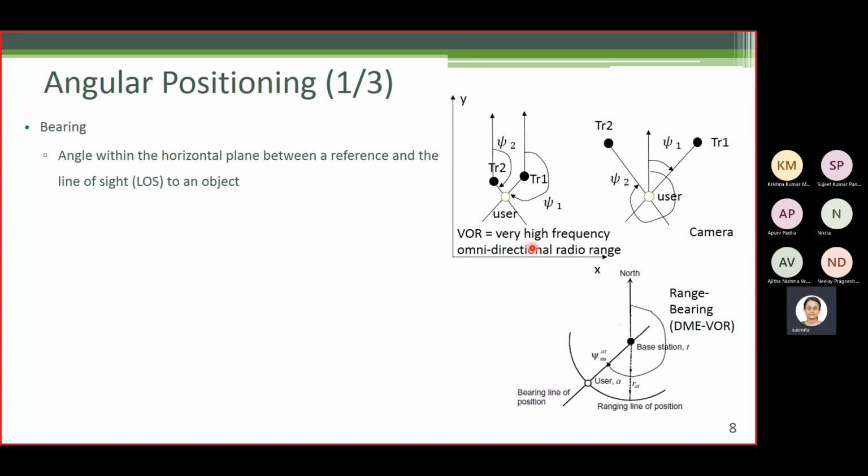So accuracy degrades as the distance between the user and transmitter increases. So the accuracy with VOR was not so good. Now, after GNSS came into being, with the help of GNSS, DME and LORAN, much better accuracy was achieved. That's why for civil aircraft, VORs are being decommissioned now.